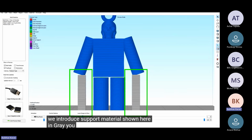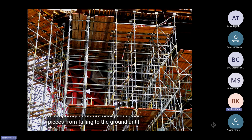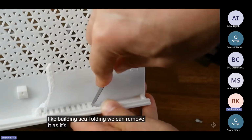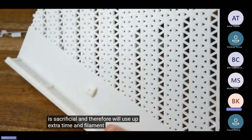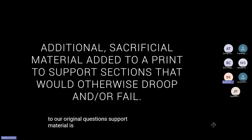You can think of support material like scaffolding on a building, a temporary structure designed to hold pieces from falling to the ground until the rest of the structure is completed. And once the structure is complete, just like building scaffolding, we can remove it as it's no longer needed. This means that 3D printing support material is sacrificial and therefore will use up extra time and filament. So coming back to our original questions, support material is additional sacrificial plastic that we add to the print to support sections that would otherwise droop down and possibly cause the print to fail.